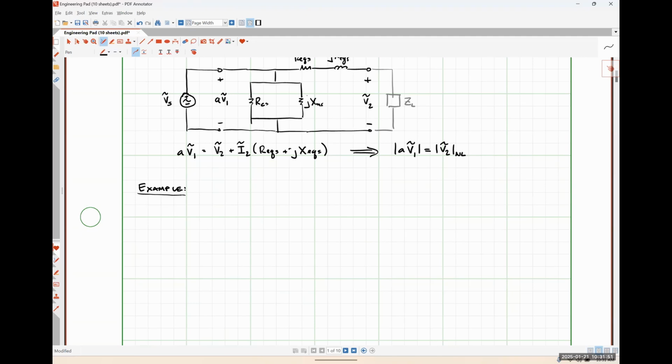So any kind of residence is definitely going to be connected to the secondary side of a step-down transformer. But chances are, even in a commercial or industrial setting, you're also going to be connected to the secondary side of a step-down transformer, because it's not a whole lot of processes that require access to tens to hundreds of kilovolts RMS. Did that answer your question?